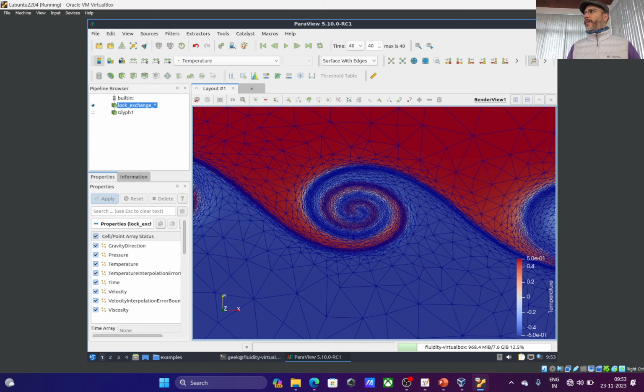It's difficult to discuss. It requires a lot of mathematical understanding and so on. But you can think of some sort of an error that is calculated, and we say that the error is much larger. So you sort of scale the error with the gradient of the temperature. So gradient of temperature is large at the boundaries. Right? It's actually not the gradient; it's a second derivative, called the Hessian. But you sort of scale your mesh size with something like the gradient of temperature.